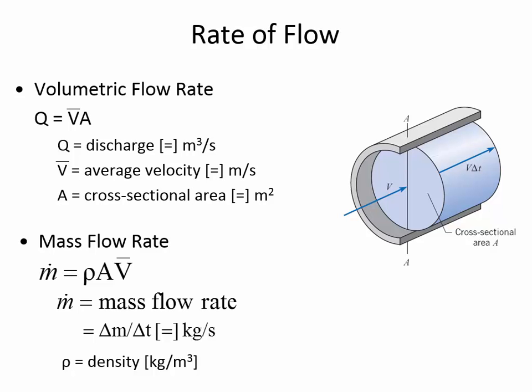Volumetric flow rate works great if it's an incompressible fluid, like a liquid, because it'll allow us to say that there's conservation, and we'll talk about conservation in a moment. You maybe have heard me say previously, when we were talking about convective acceleration, for example, that if you have 1 liter of water that goes into the pipe, then a liter has to go out.